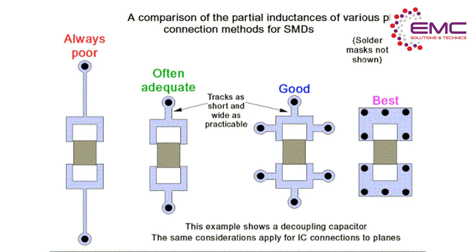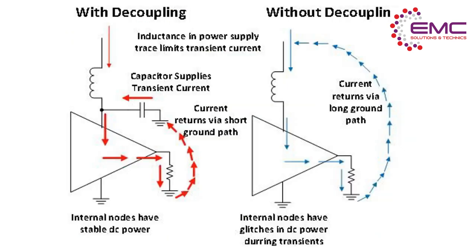This path should be kept to a minimum possible level by placing a decoupling capacitor very close to the IC, see figure. A large ground loop increases the radiation and can act as a potential source of EMC failure. The reactance of an ideal capacitor approaches zero with increasing frequency. However, there is no such thing as an ideal capacitor available on the market. In addition, the lead and the IC package add inductance as well. Multiple capacitors with low equivalent series inductance, ESL, should be used to improve the decoupling effect.